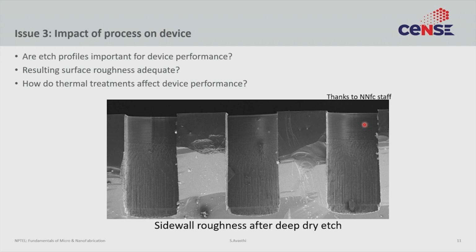So questions like that. We already discussed the effect of thermal treatment, right? If you have aluminum already, maybe you should not be subjecting it to any anneals that are 800 degrees C. If you already have metal, maybe you should not do any cleaning that involves acid.